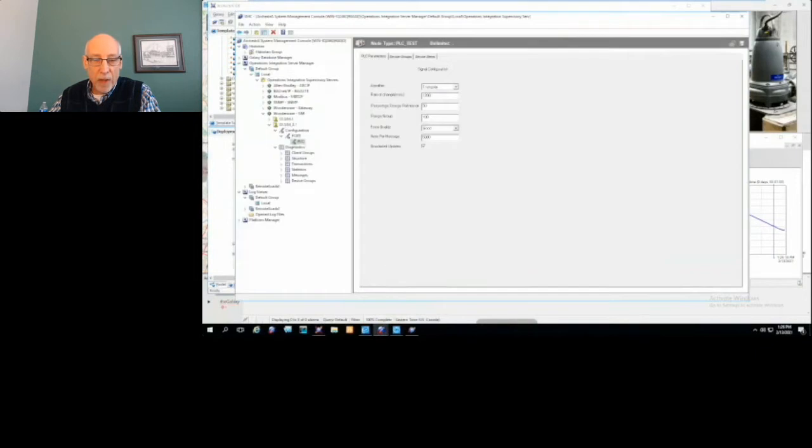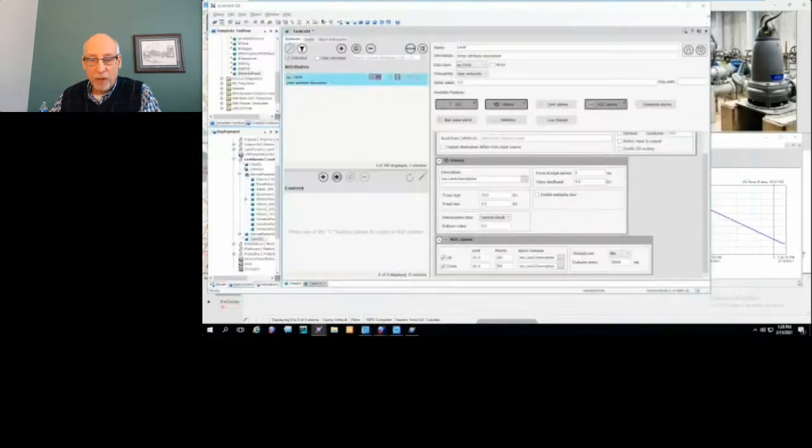And so I go into my I/O simulation, I set up a port, I set up a PLC here, and I choose the algorithm that I want. I can choose a triangle wave, which I'm going to use in this case, but I have other options here. I can have a random number generator or a sawtooth wave. So it's a great tool to be able to generate some simulation data for our testing here. So I'm going to use this tool to generate some slopes of the line that we're going to look at to generate these deviation alarms.